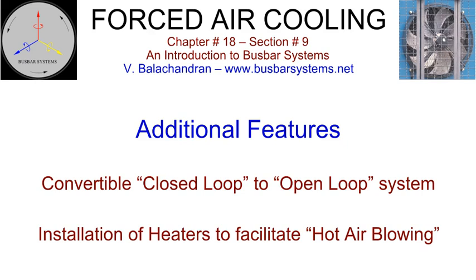Forced air cooling systems, where installed, can also be used to clear the moisture and dust from inside the isolated phase bus before energizing the same after a period of shutdown. Provision can be made to heat the inlet air to the desired temperature before circulating it inside the isolated phase bus. Those sections of the isolated phase bus that are not included in the forced air cooling circuit can be subjected to hot air blowing from a portable device.